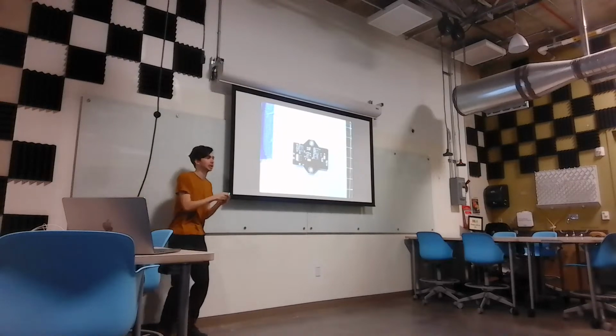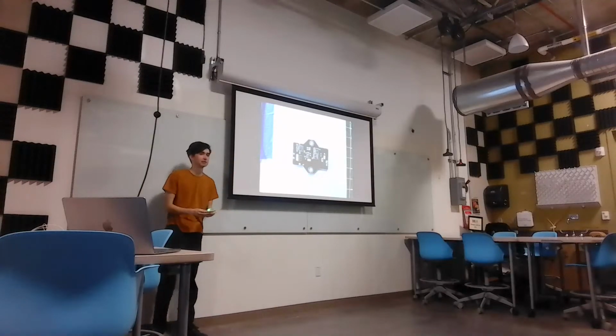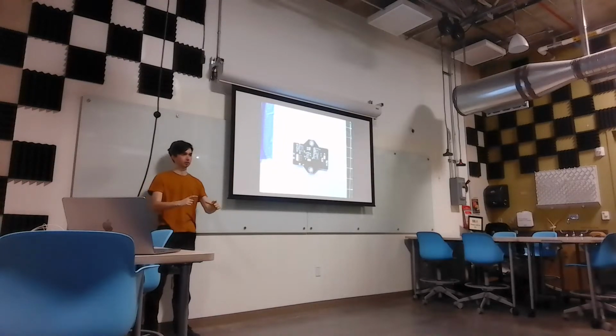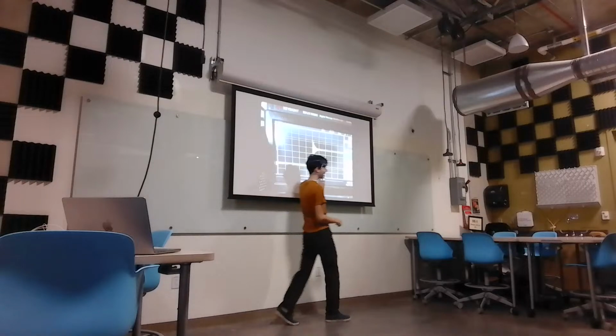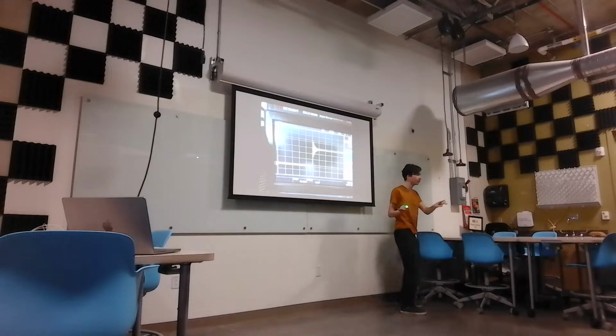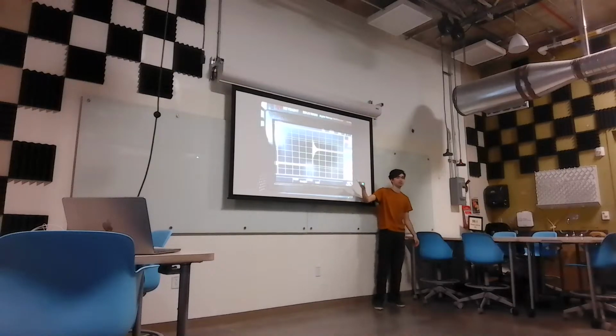They talked about how you need to make sure that the current loops are sufficiently small, because the bigger the area of your loops are, the more it is an antenna. That's exactly what this was. An antenna. Check that out. That's bad. Here's the thing though, improvement, the frequency of the oscillation is really high. It's 85 megahertz in this picture.